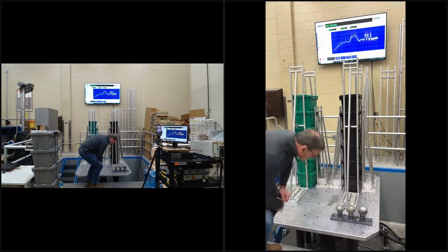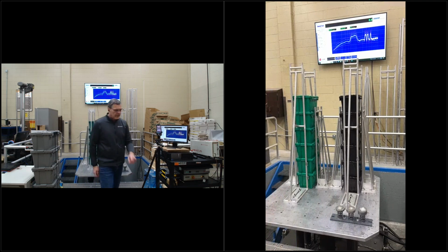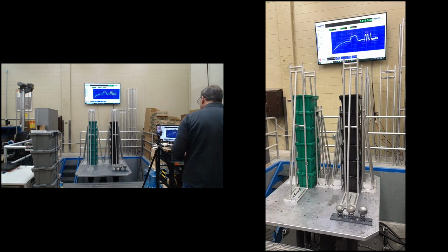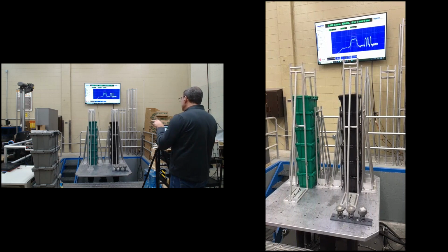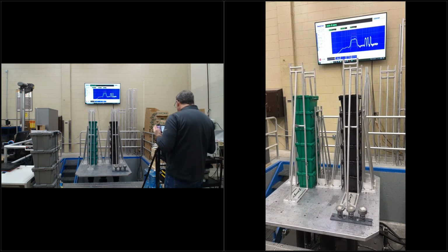But I'm able to add big energy inputs at each of their distinct natural frequencies, all as part of this PSD that I can play around with and program to tune specific frequency content. If my goal is to seriously challenge each and every one of those, the stacks and the springs, I can do so.